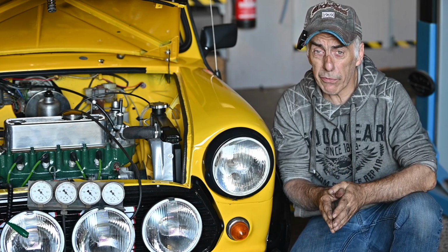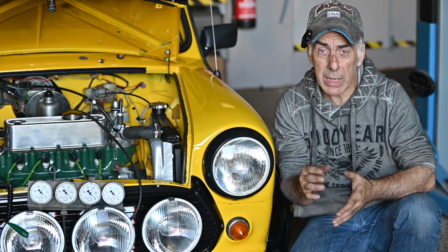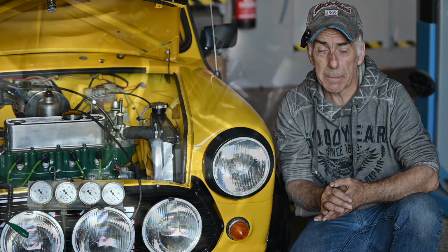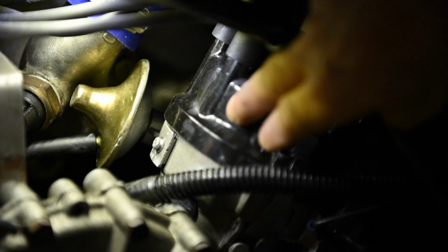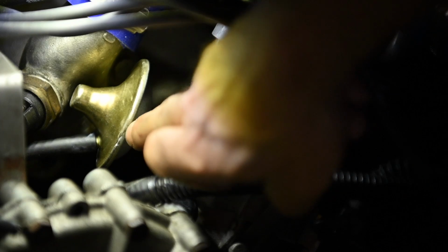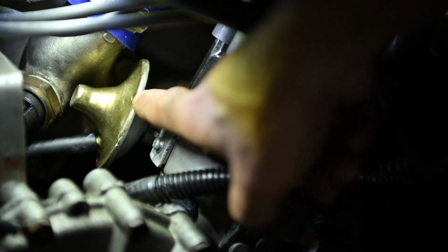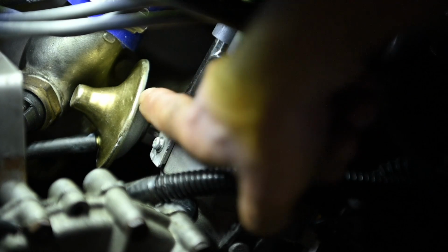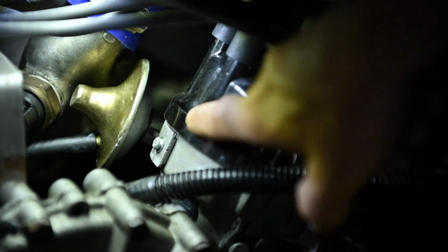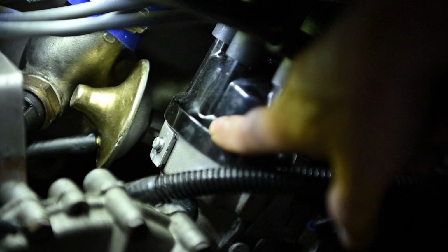Vacuum advance, and often you see a combination of bob weights and vacuum advance. This is an example of a distributor with a vacuum advance, and this is the membrane connected to the intake manifold under pressure or vacuum, and whenever the engine is running, it's going to move that membrane inside that way, and as such it's going to pull a little rod inside that will advance the notch inside the distributor.